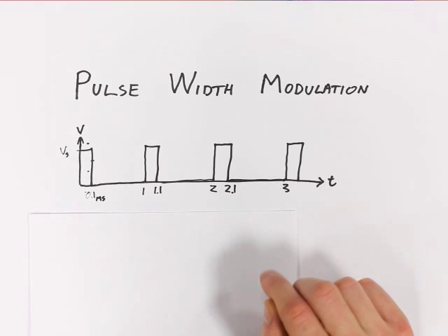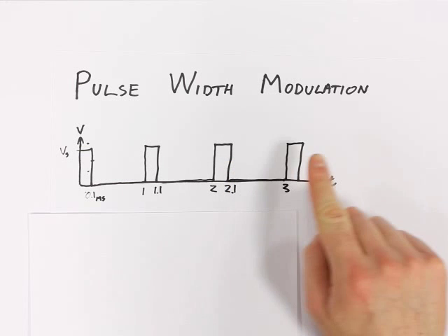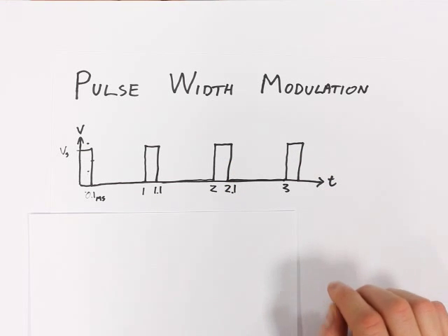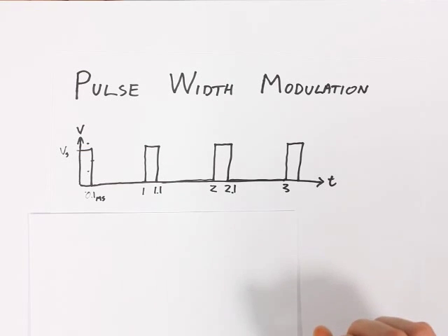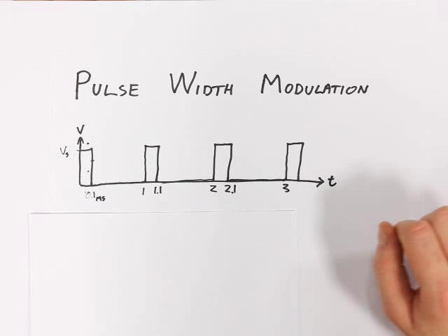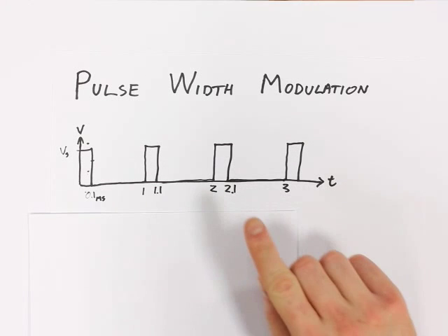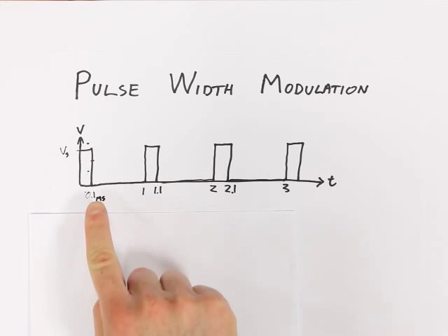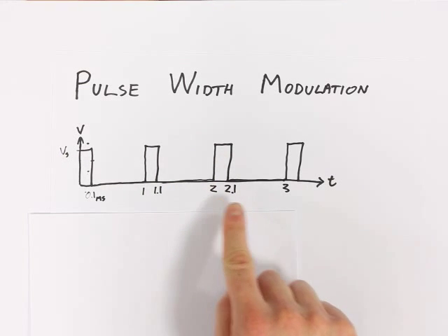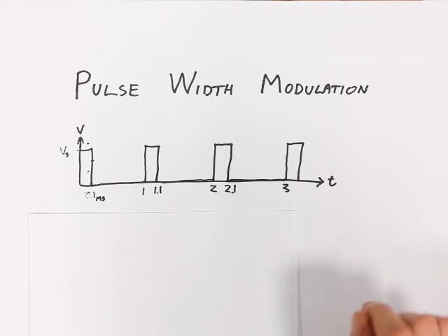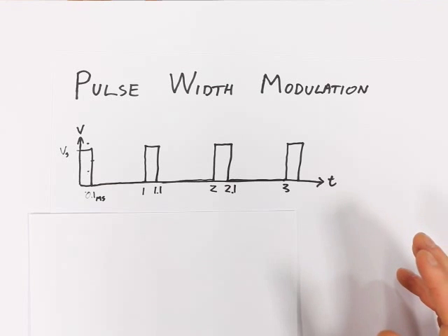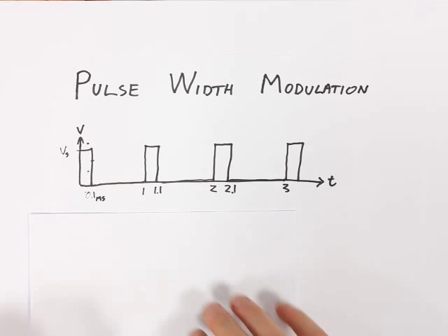Okay, now we're going to look at one final interesting modification, which is pulse width modulation, or PWM. If you watch the CECC videos from the previous 6002X course, you may have seen this technique used by Alex for speed control of a DC motor. And in a similar application, we're going to use it to control the intensity of our LED. What PWM is, is where we apply brief pulses of voltage to our device rather than one continuous voltage. And this is useful for modulating devices which only like to operate at one power level, where they can only be 100% on or fully off.